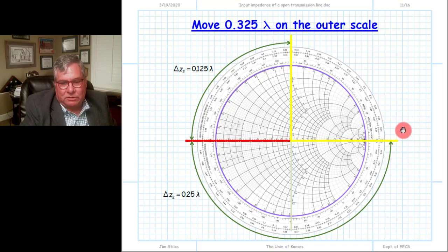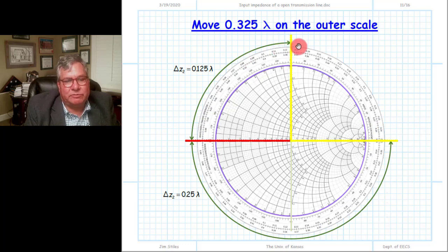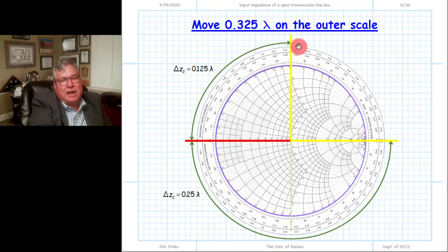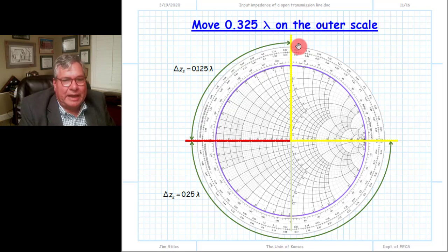And here's the graphical representation of what I just said. There's a typo here. There should actually be Z1 and not Z2. The first step, we rotate around a quarter of a wavelength, and then we rotate an eighth of a wavelength. And that gives us, of course, 3/4 of a wavelength around the Smith chart, 3/4 of a wavelength from the end of the line where the open circuit load is, all the way back to the input of that terminated transmission line.